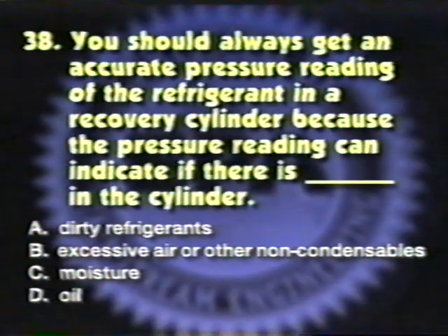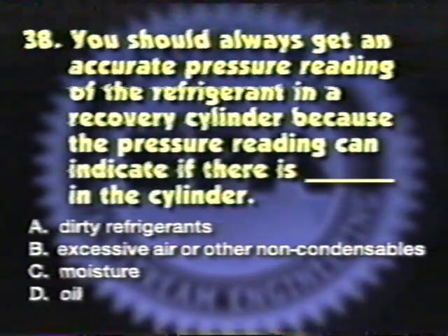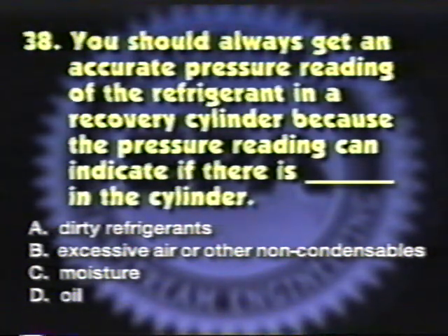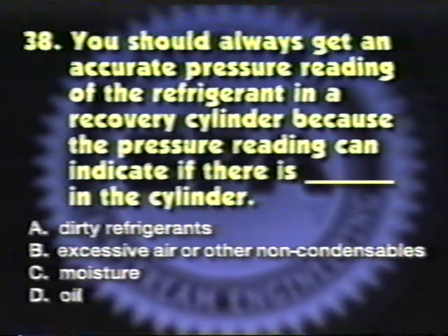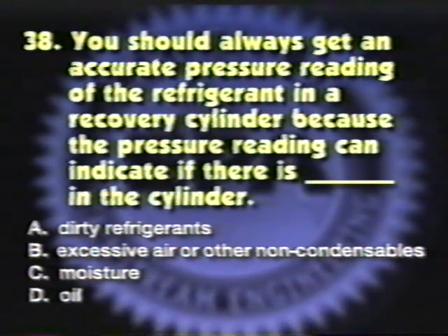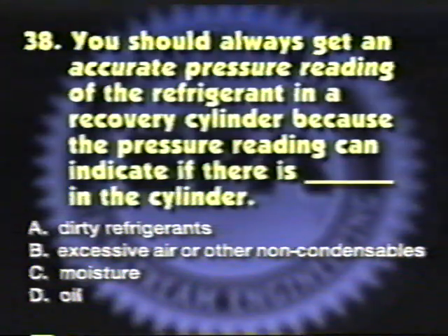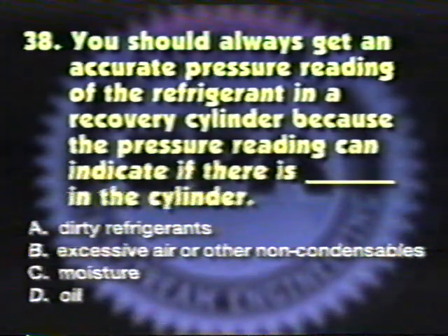You should always get an accurate pressure reading of the refrigerant in a recovery cylinder because the pressure reading can indicate if there is which of the following in the cylinder. A. Dirty refrigerants, B. Excessive air or other non-condensables, C. Moisture, D. Oil.